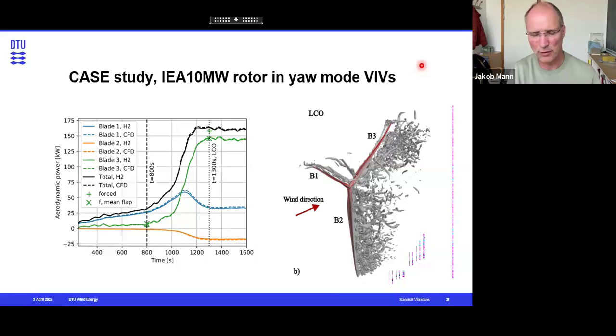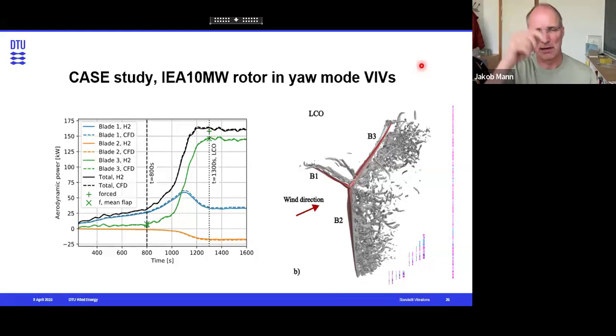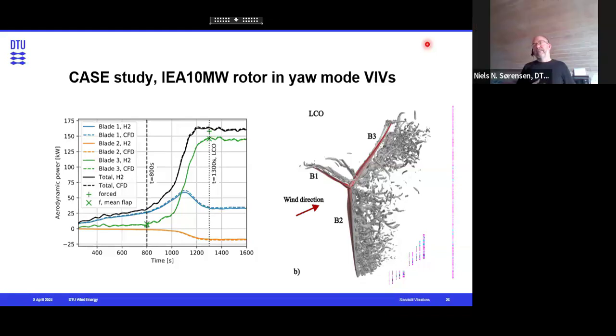All right. In the first case, steel chimneys have these spiral things on them to prevent this. Could you imagine something similar here, that you could put those on during installation and then take them off when you start the turbine? These are things that I guess our industry partners prefer not to discuss with us.